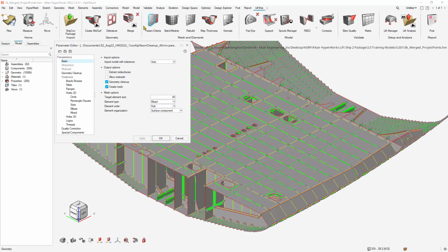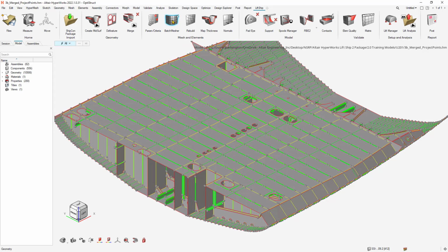One thing I forgot to mention is you can save those. You may want to take a few parts in your assembly, apply the mesh, check if it's the appropriate quality and executing as you expect, and then save that as your project's param and criteria file and reuse that for your team. It helps with standardization, as well as being used in the batch mesher.